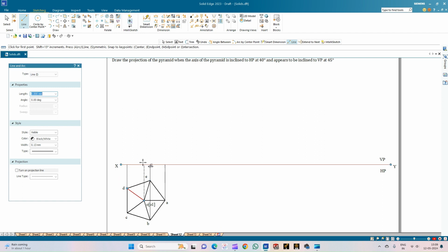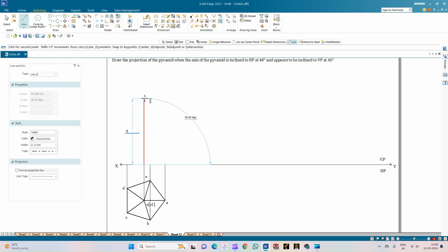So now we have got the point from where the axis could be drawn. So let us go for the chain line, and from here let us draw the axis of length 50 mm and also complete the front view. So for that, select the continuous line of thickness 0.50 mm and connect the end point of each projection lines.